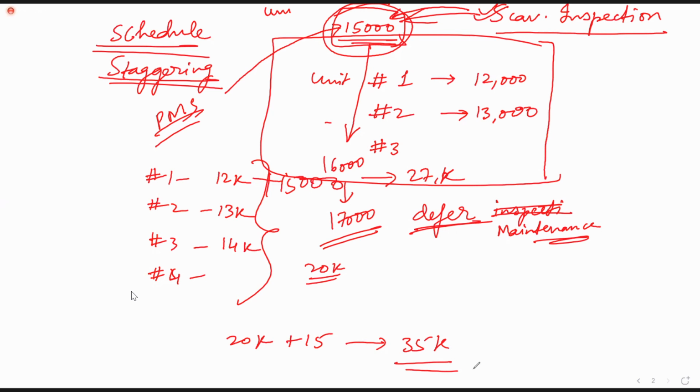all the units never behave the same way. Like all fingers in your hand, they don't behave the same way. They are not of the same size. They don't work the same way. So like this, all units, in spite of being identical in the beginning, and the maker having designed them identically, do not continue to operate the same way for the entire life. Somewhere the combustion is better, somewhere it is slightly less better, somewhere it is poor. And like this, the condition continues to get altered, and so is the wear condition, and other conditions inside the cylinder continue to be different. Is that clear?